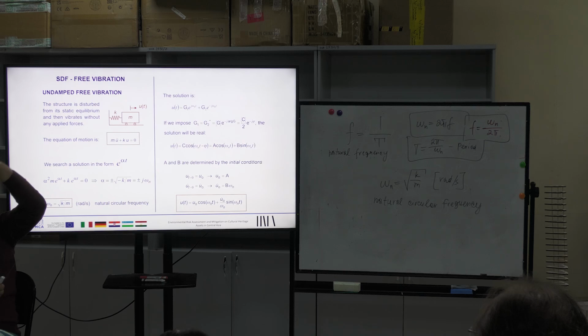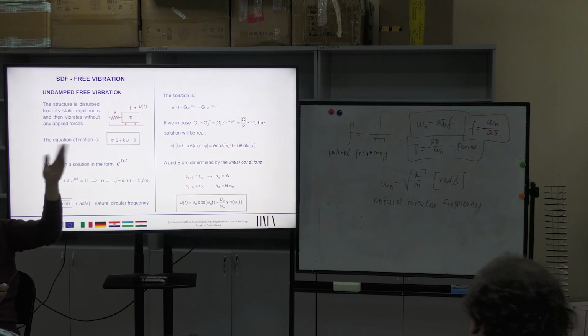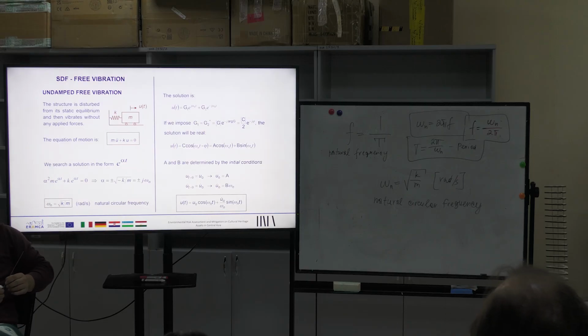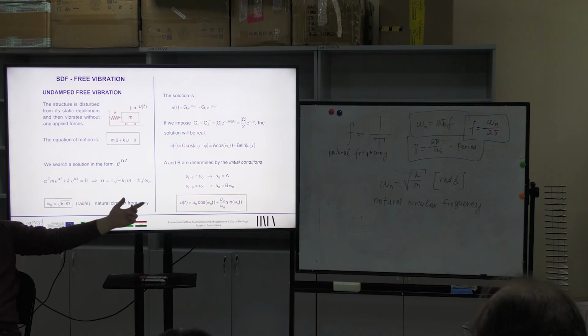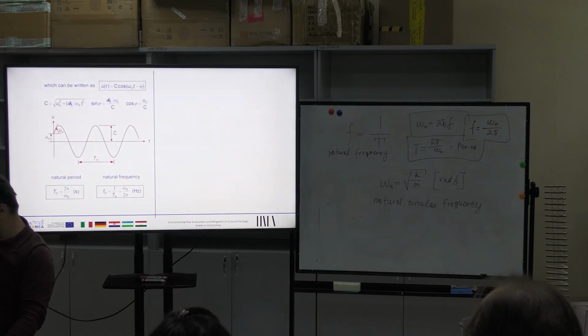For instance, if you have a 2-floor house, maybe its natural frequency is 5 Hz. If you give a 5 Hz signal, your building can accept its own natural frequency, and its amplitude is going to increase, okay? So the main purpose of analyzing the building is to find the circular and natural frequencies and the periods, okay? Okay, good. I have explained this already.